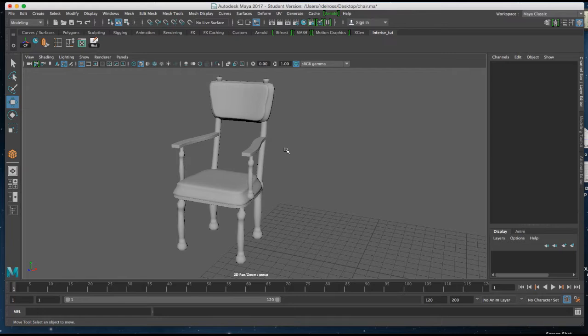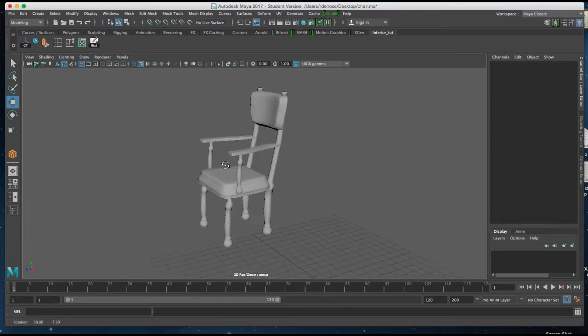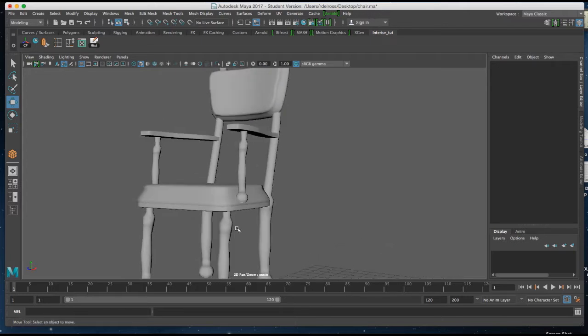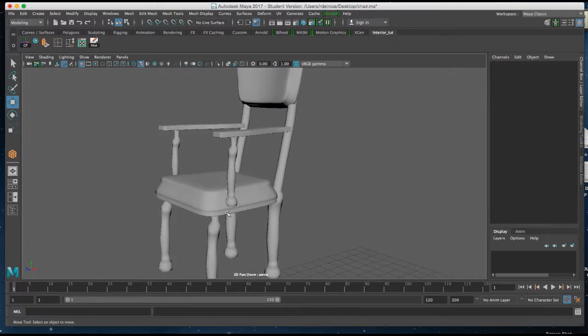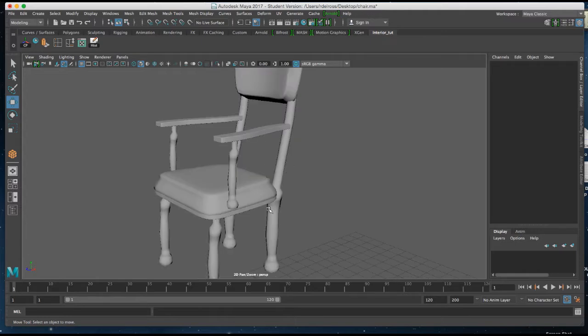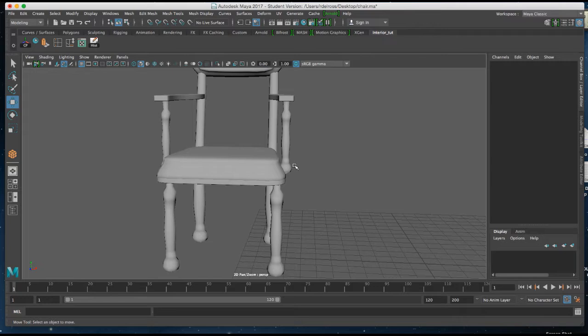In this next tutorial, we're going to address making this chair. So the legs and the arms here, you can see, are nothing more than duplicates of the front legs. The front legs are duplicated back legs, deleting the top. We will start with one piece of geometry and then just populate our chair with the pieces we need.